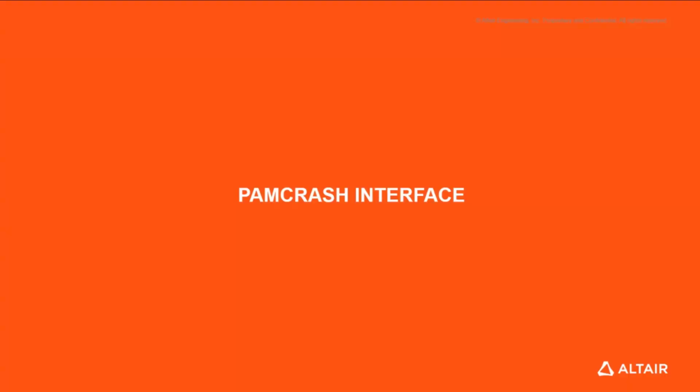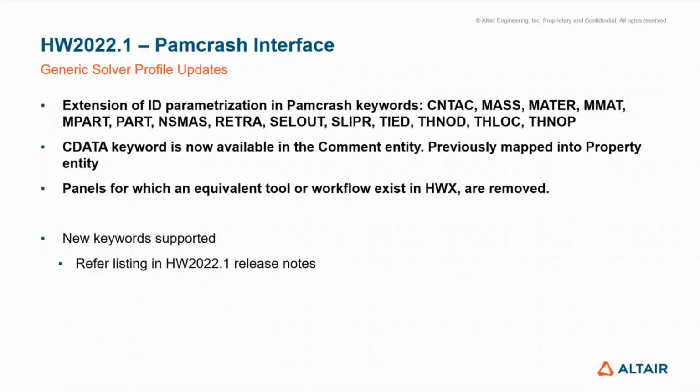For the PAM-Crash interface, here as well, a couple of generic solver profile updates. The main improvement in this release for the PAM-Crash solver profile is the extension of the ID parameterization for a lot of new keywords, which were not supported before. So now we have full-fledged ID parameterization support in PAM-Crash.